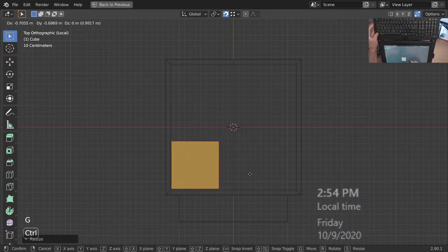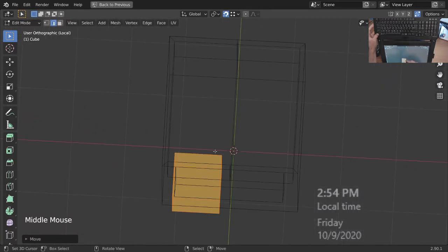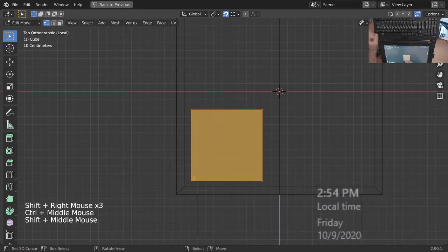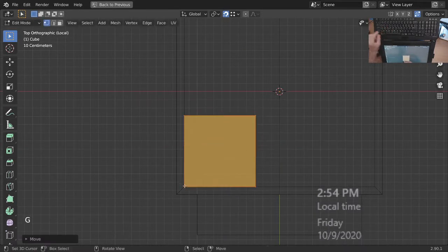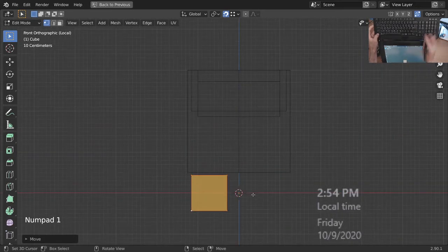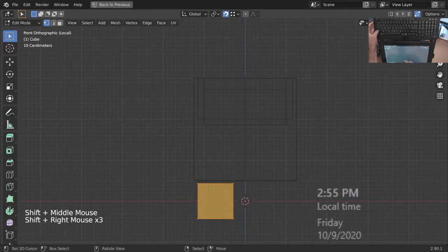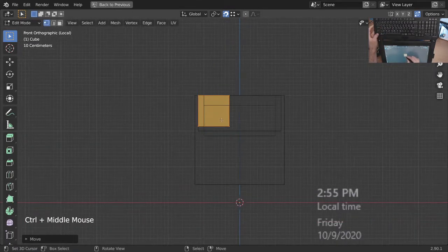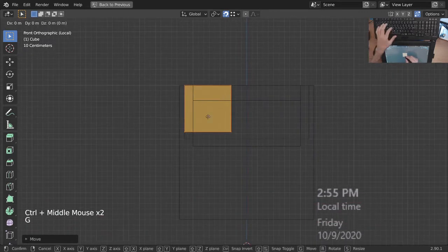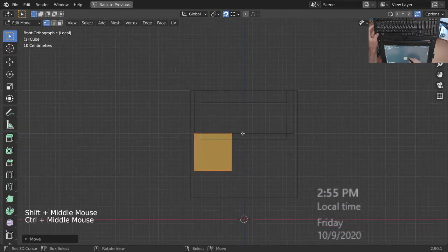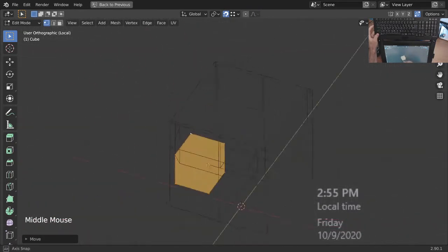Grab it. Seven. I'm going to go into the vertices. Select one active vertex right there. Grab Shift Z and then snap there. Now I'm going to the front view, make one of those vertices active, and then grab Z and put it up. No, not there. Grab Z, put it down here somewhere. So that's the cube where it's going to fall into.